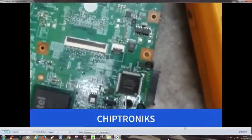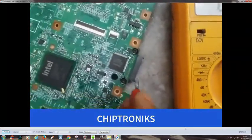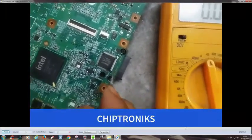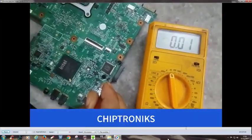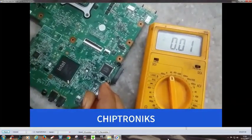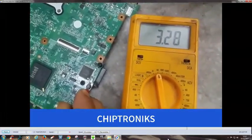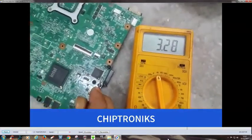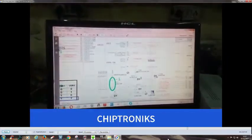At this IO controller we will check at pin number 15 whether this S5_ENABLE is coming or not. And our IO is U1773. So let's check at pin number 15. And you can see at pin number 15 you can find 3.28 volt, that is 3.3 volt, that is correct voltage.